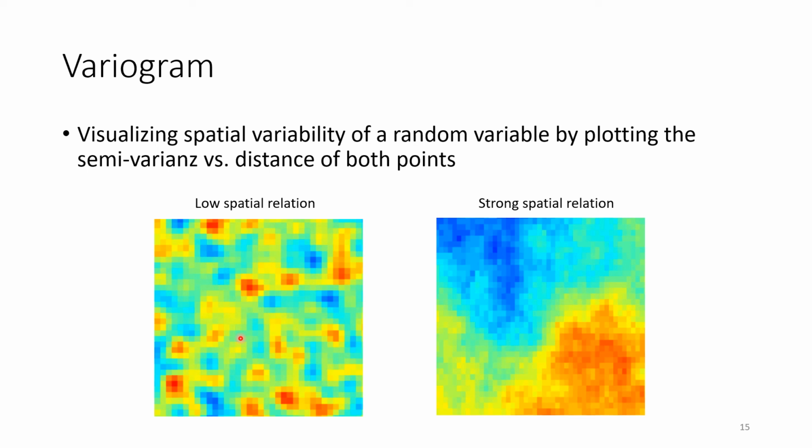And this characteristic is then already incorporated in your model, and you can run a couple of models, but of course the exact concentration value would vary, while the overall behavior of the solute transport would look similar. So this is really an important point which you can include into your model, maybe even without the exact parameters. That's why I say you can do parameter variations to cope with that. If you have enough data points, you can use interpolation techniques such as kriging or other ones to include it.